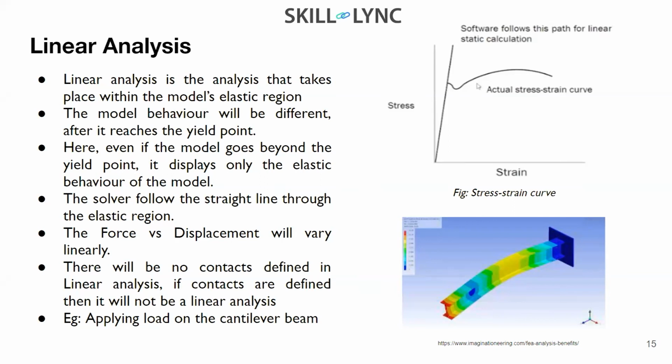Okay, so as I said, the solver follows a straight line throughout the elastic region. The force versus displacement graph will vary linearly. So there will be no points of defining contacts in linear analysis. Okay, so that is one thing.